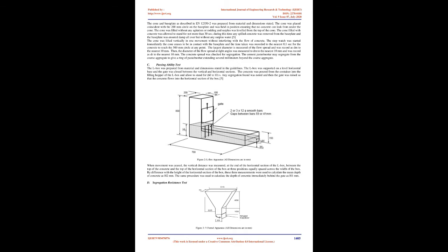The trial mix design was based on the evaluation of the water demand and optimization of the flow and stability of the paste, determination of the proportion of sand, coarse aggregates, and the doses of admixture to give the required robustness, test for the sensitivity to small variations in quantities, addition of an appropriate amount of coarse aggregate, production of the fresh SCC in the laboratory mixer, performing the required tests, and the compressive strength of the SCC in the hardened state was calculated by recording breaking load of concrete cubes.